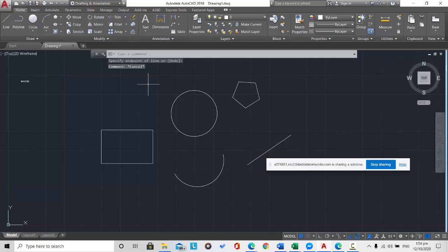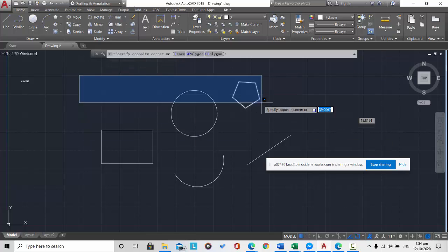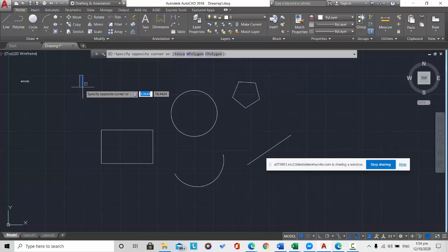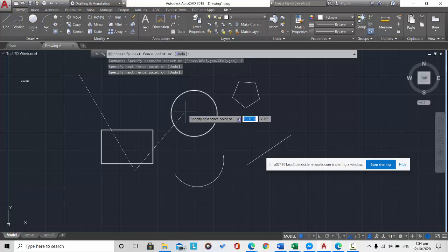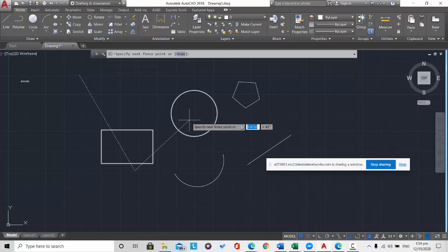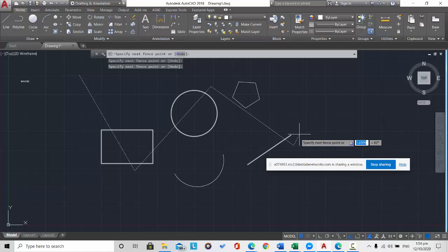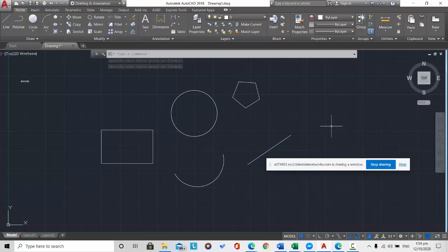But I think the easiest selection, kasi for example you have plenty of objects in your workspace, the easiest to use is the fence, because the fence allows you to move your objects in different directions, no? Rather than clicking one by one the object, you can use lines to select just the objects that you need to select. So all the objects that are passed by the line will be selected, no? Like for example in that case. Okay, so that's an example.